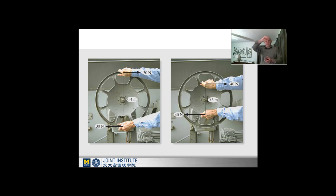So we have 30 newtons applied in one hand, 30 newtons applied in the other hand, both perpendicular to the position vectors, so that you're applying the maximum efficiency of turning, and that would give us 30 newtons times 0.4, and that would be our moment.